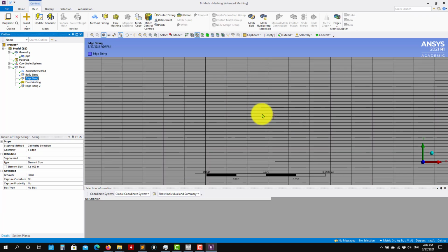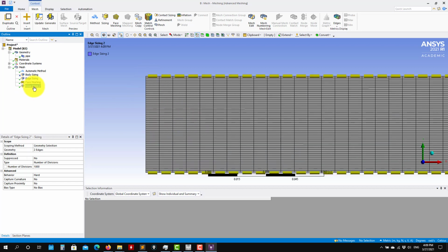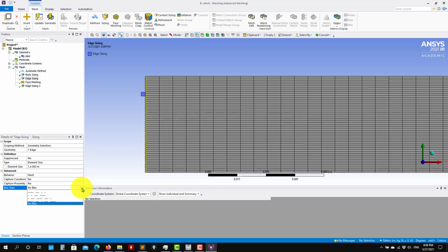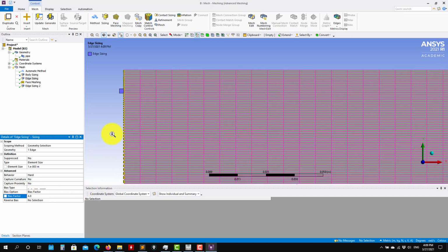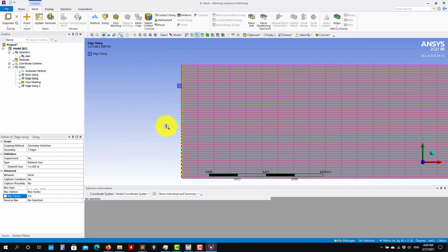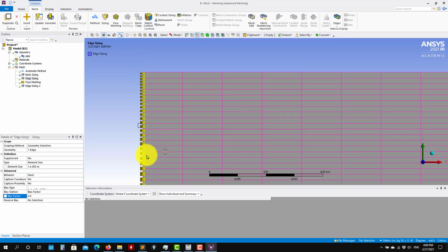Now see that we have this, perfect, beautiful. So now how do we control this stretching for this kind of meshes? Here you have an option called bias. So now let's control the bias. I want to bias, you have different options there. And let me add a bias factor of 4. Again, in the documentation, you will see how this bias factor is computed. I don't recall if it is a function, maybe a power law function. But see that this is just clustering more cells there.